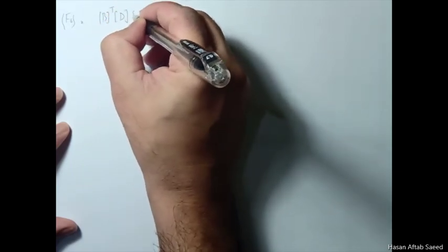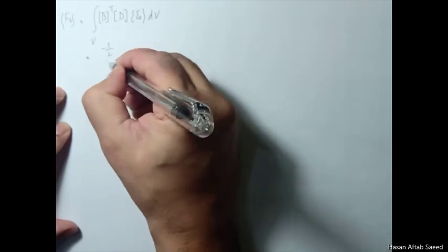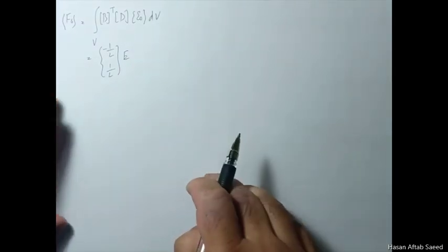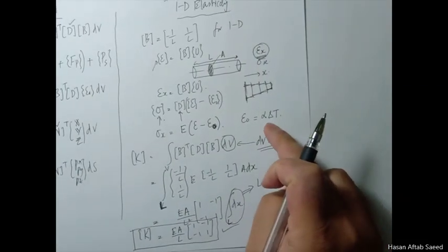Now if we move on to our next vector, which is the temperature effects. Whenever a 1D problem involves change of temperature, again just copying from the expression we have derived earlier, let's put in the values again. Minus, and the B is a transpose, so D is simply E, and epsilon naught, like we discussed, for a 1D problem is simply alpha delta T.